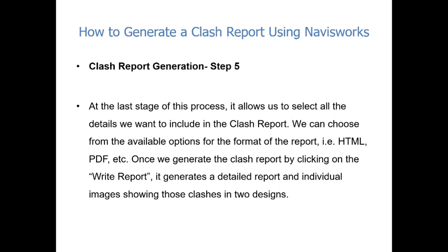I generally ask the students to generate an HTML-based clash report because it's easier. I can open it from my web browser and see the clashes with the images with the file. That HTML file will be one subcomponent of the second submission. Once we generate the clash report, it generates a detailed report and individual images, so screenshots of each clash, showing those clashes in the two designs.